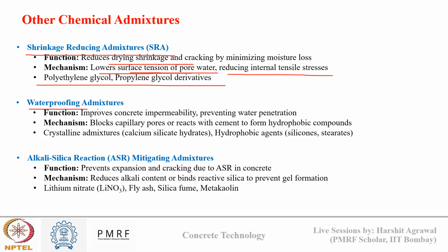We have waterproofing admixtures, which improve the concrete's impermeability, so they don't allow water to penetrate inside concrete. They work by blocking the pores inside the concrete and reacting with the cement to form a hydrophobic compound. These include crystalline admixtures, hydrophobic agents, and so on.